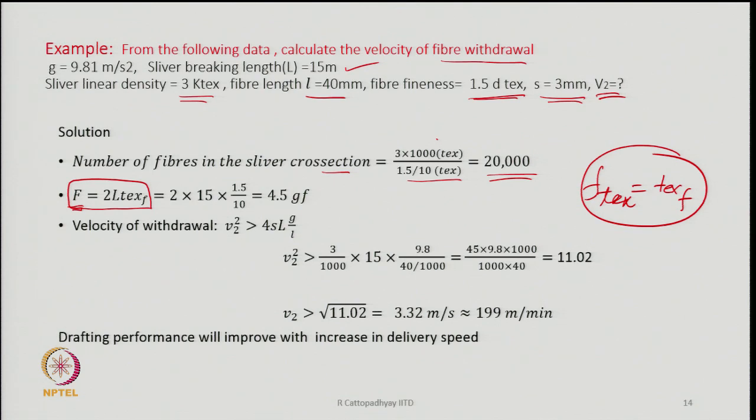So, this is the force that you need to withdraw a fiber, following the previous same expression, and that gives you a value of 4.5 gram force.